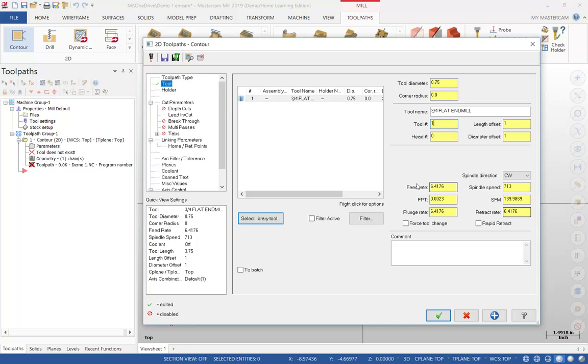If this is not cutting, when the tool is coming down, this is the down motion. When this coming down is not cutting, you can actually speed it up to 30 or 40. It doesn't matter, so that it speeds up the machine time. The same goes for the retract rate, this is going up.